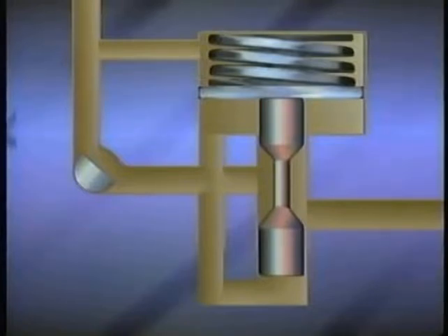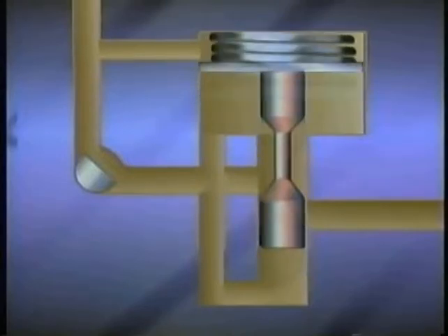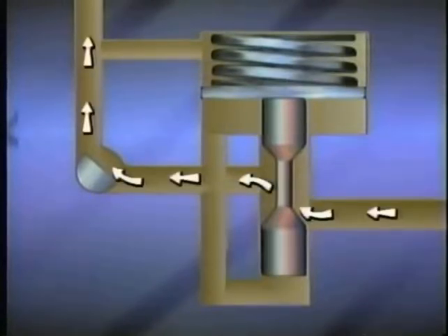Basically, in response to changes in inlet and outlet pressure, the spool can move up to close the inlet, or the spool moves down to open the inlet. This allows only that amount of fluid to enter the valve that can be forced through the throttle.